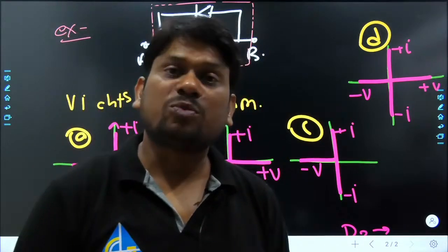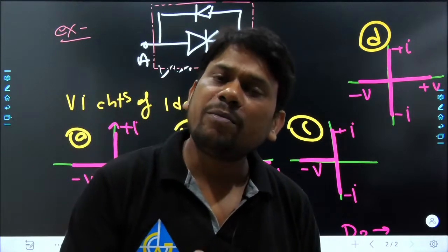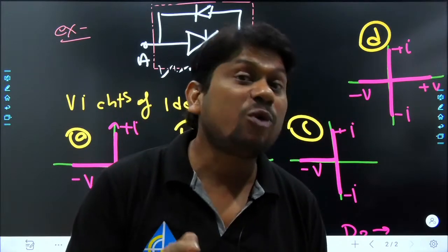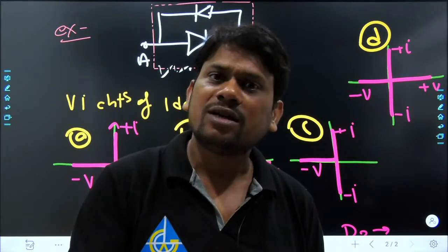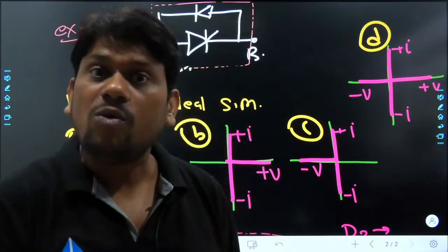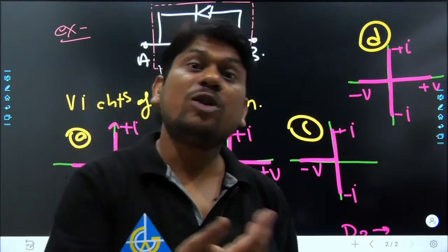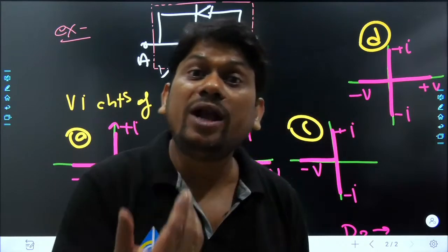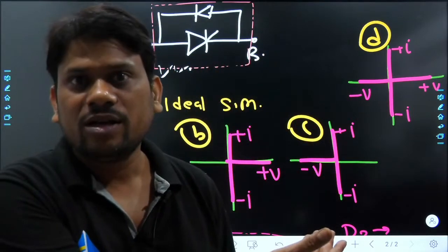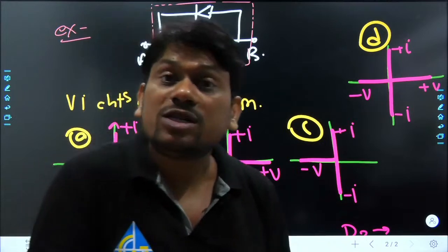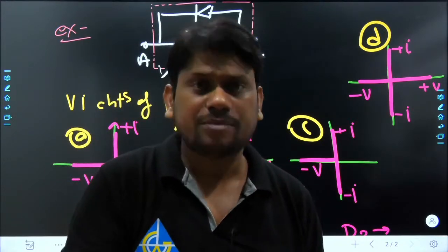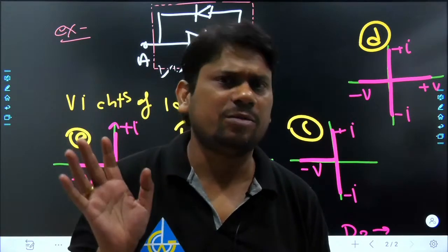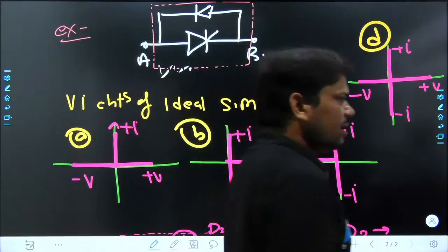You are not correct at this moment, because a diode can block voltage only when it is reverse biased, and once it is forward biased, it will not block any voltage, and we don't even want to allow that. When our diode is on, the entire voltage we apply across the terminals will appear across the load. So when devices are on, they are not responsible for blocking any voltage. This is a simple thing. Okay? Now tell me.